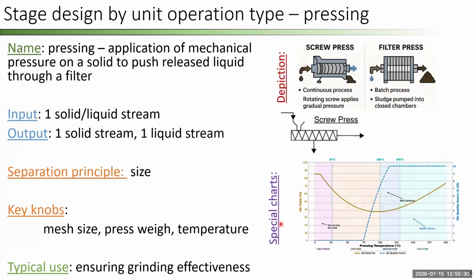Okay, the filtering is often used in combination with pressing. So here we have a mechanical application of a mechanical pressure on the solid liquid suspension that's going to push released liquid through a filter. Okay, so here we have one liquid or solid stream, and then again, we're going to end up with one solid stream and one liquid stream.